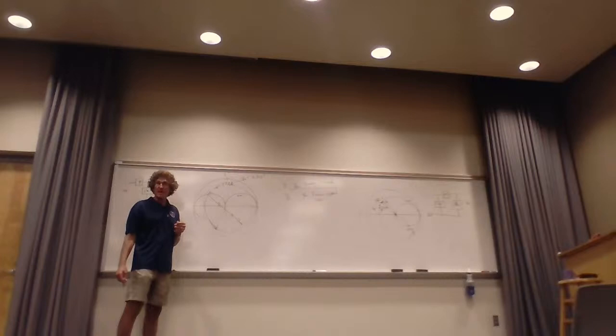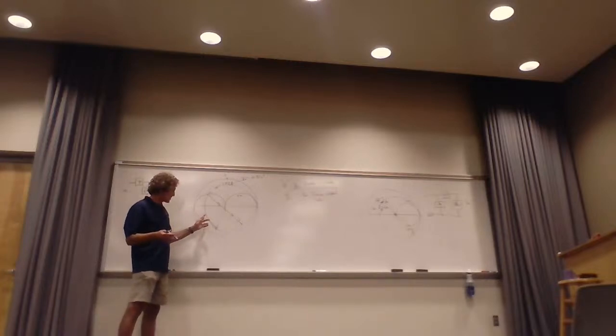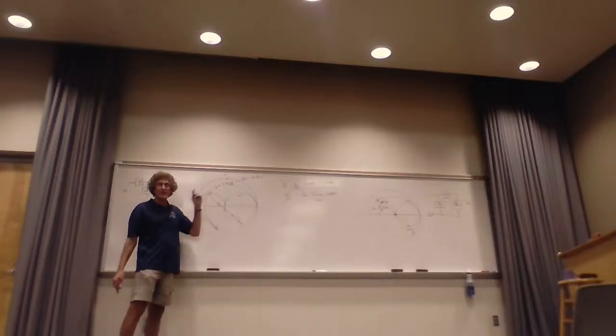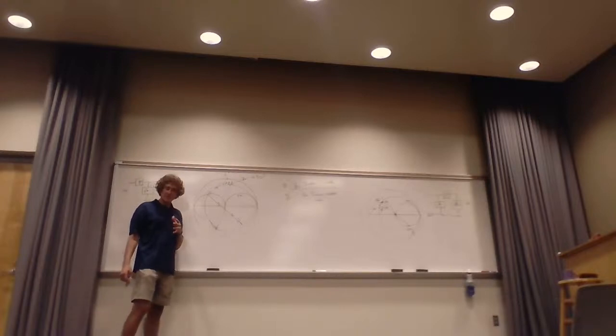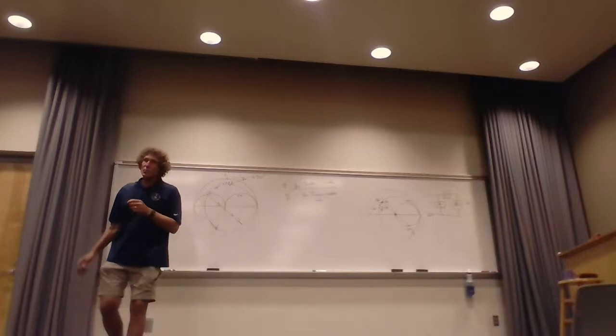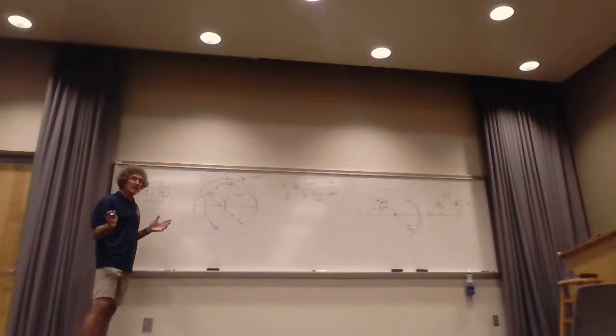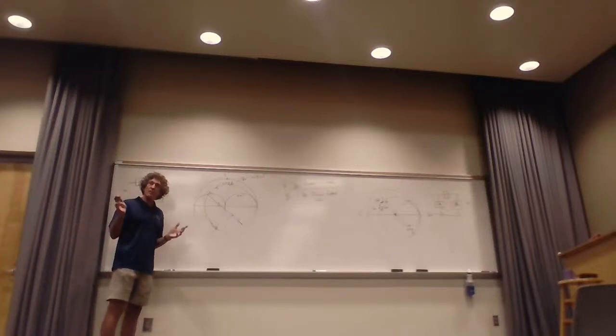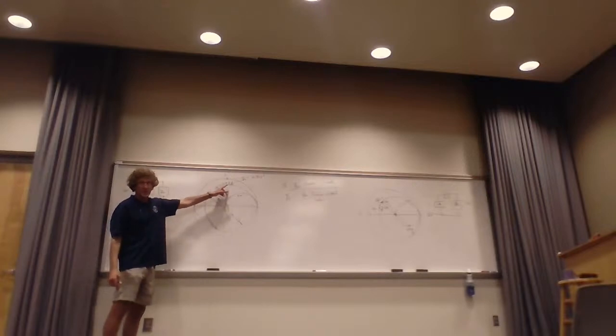And if you don't want a capacitor in series, then you would go to the admittance domain and you would have a capacitor in parallel. Do y'all follow me in that class? And then you could get to this circle and then from here, go to here, and you can mess with it. But I'm just going to tell you one thing. With these things, the key is if you want an inductor or capacitor in series or parallel, it's in the beginning.